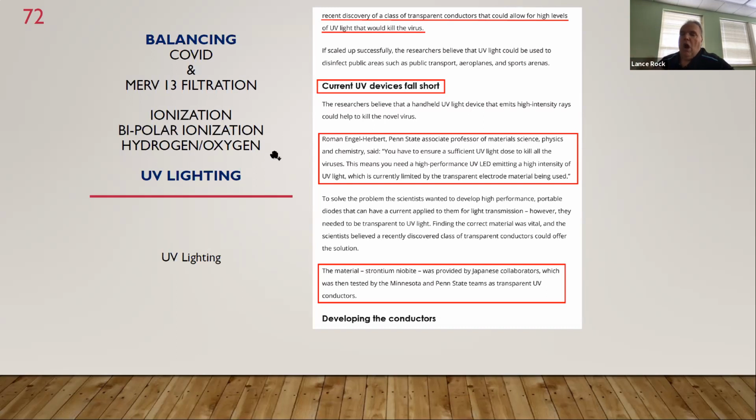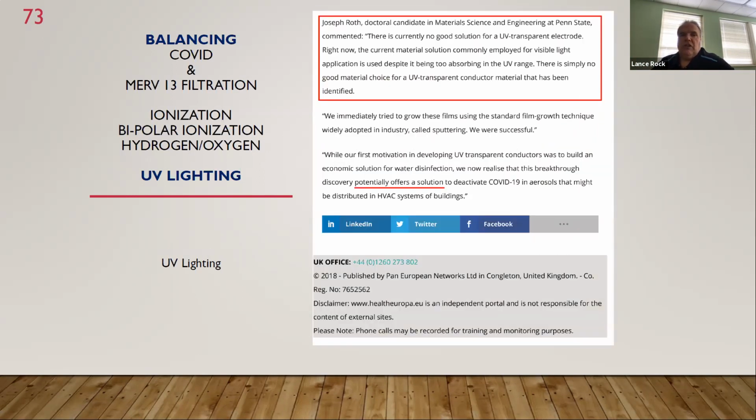Having it wash the filters where that was caught is a good thing to have, but it's not a cure-all for a ventilation system. Increased outside air is flushing of a building, air changes. And that's only done with outside air. It's not done with a 100,000 system moving 100,000 CFM with only 1,000 CFM outside air. That is your effective air change rate that you use, 100 CFM, not a 100,000 CFM supply return system. Next, please. 7 more slides.